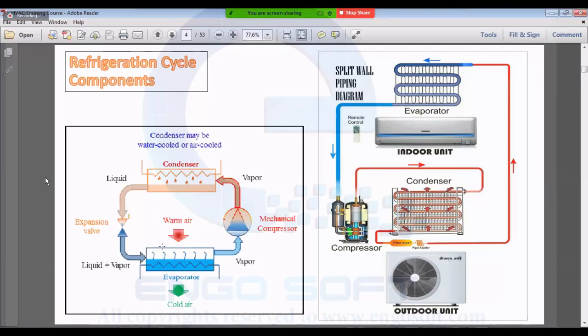Relative to the ambient temperature, or the space temperature, which is at 24 degrees Celsius, the ambient temperature is hotter than the Freon, right? Yes. So the space here is heating the Freon. Now I understand.